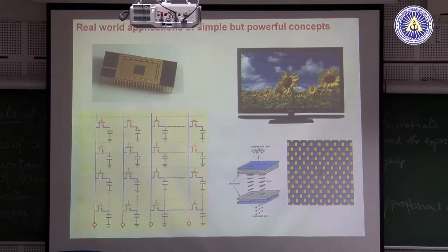An amorphous silicon or a polysilicon transistor sitting there. So this display that we are talking about, the LCD display that everybody sees in cell phones, laptops, TVs, everywhere, is also like a transistor and a capacitor. And some of the properties of an LCD display we can also understand through this simple RC circuit. So my point is, if we can take some of the very simple concepts, RC circuits and other things, and connect them to everyday life.